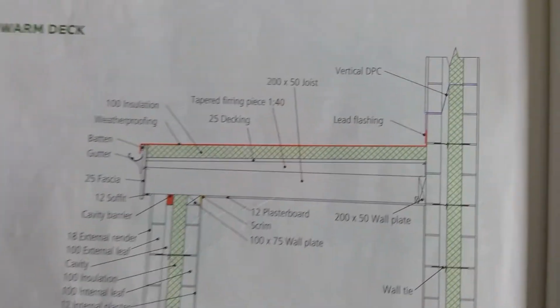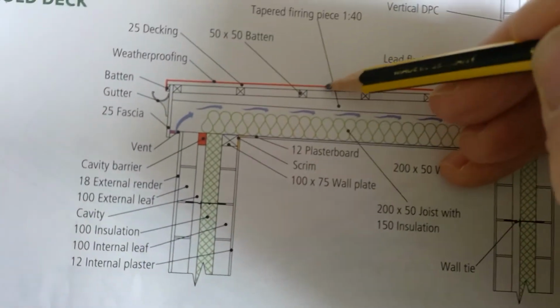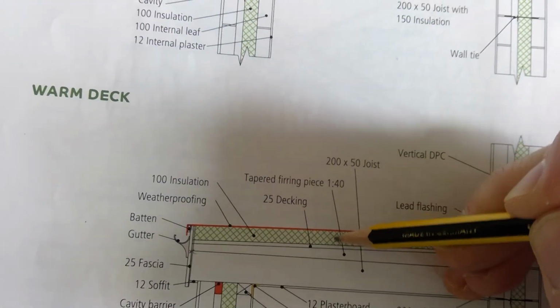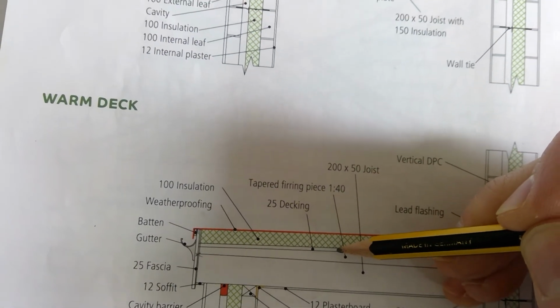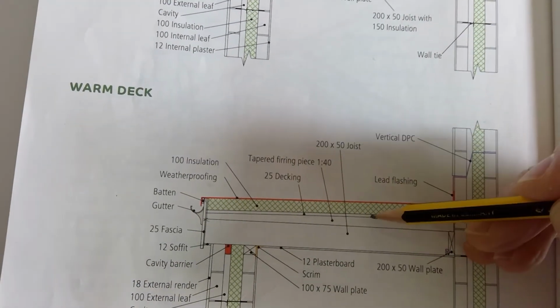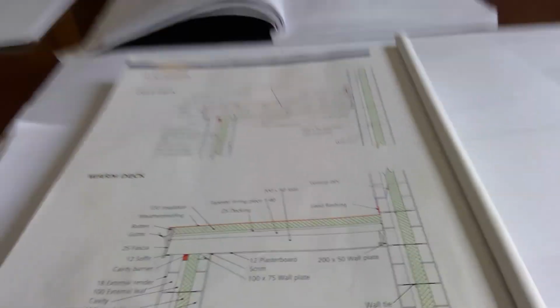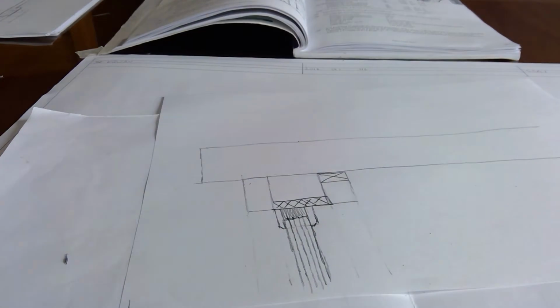The question there, you can draw either of those flat roofs to a point, but the question did specify that the felt, so this red line here, that felt that goes on top of the flat roof, it's resting on plywood. So your plywood is there. So the roof we're going to do, we're going to put our insulation in between the joists, and then we're going to have the felt resting on top of our plywood, which I'll show you in a moment. But you have a choice of either of those within reason.